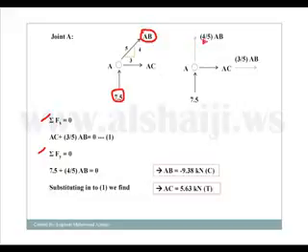The y component is 4/5 times AB, and the x component is 3/5 AB. Of course, AC is already resolved. It has only one component, along the positive x, and the 7.5, the reaction AY, is acting along the positive y. So now I'm ready to use my equilibrium equations.